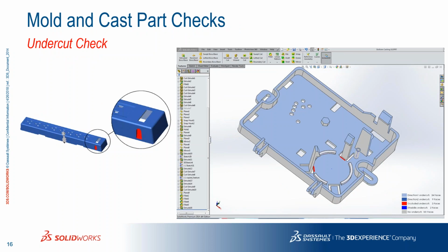And this is if you want to have a tool with two parts and an undercut tells you it's stuck. You cannot do it with two parts. Otherwise, you need to modify the geometry, or you will end up with some more expensive tool like doing more cores, more moving parts, and so on. So it's a good check to see that you have not run into some more costly area to fix this as a tool.